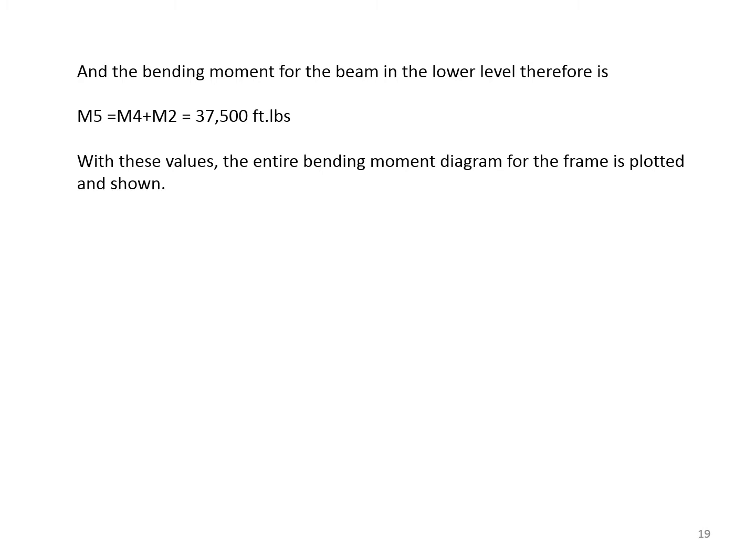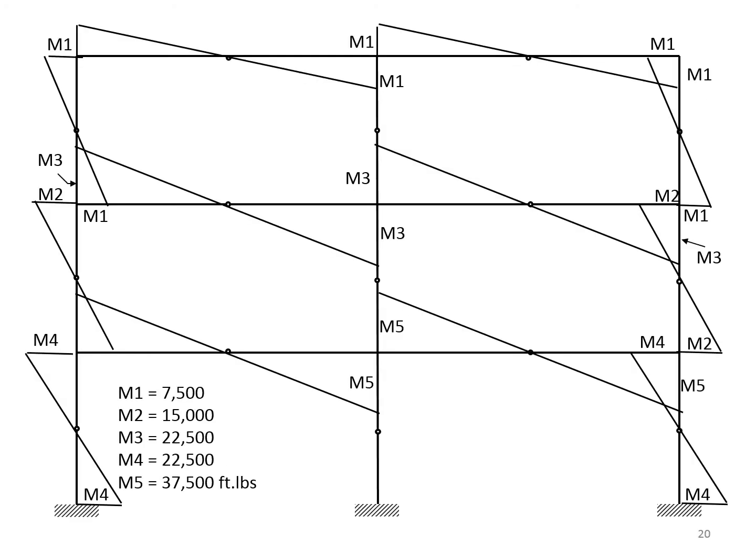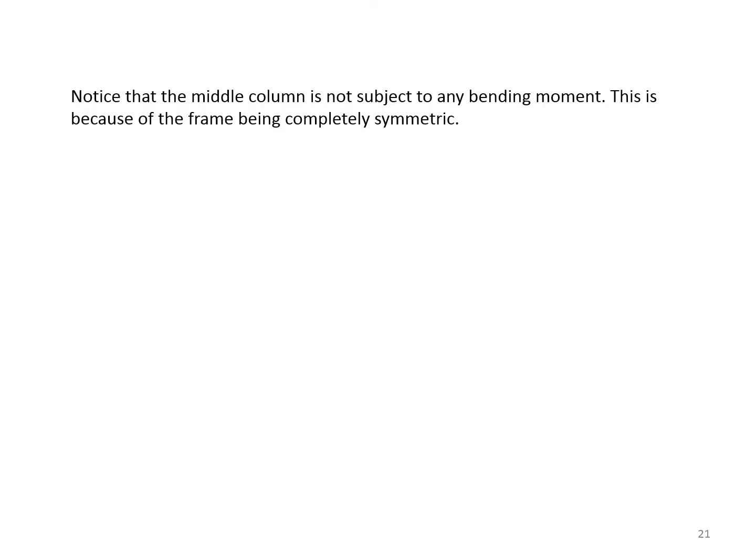With these values, the entire bending moment diagram for the frame is now plotted. Here it is. The values are listed at the bottom. Notice that the middle column is not subject to any bending moment, as we explained before. This is because of the frame being completely symmetric.